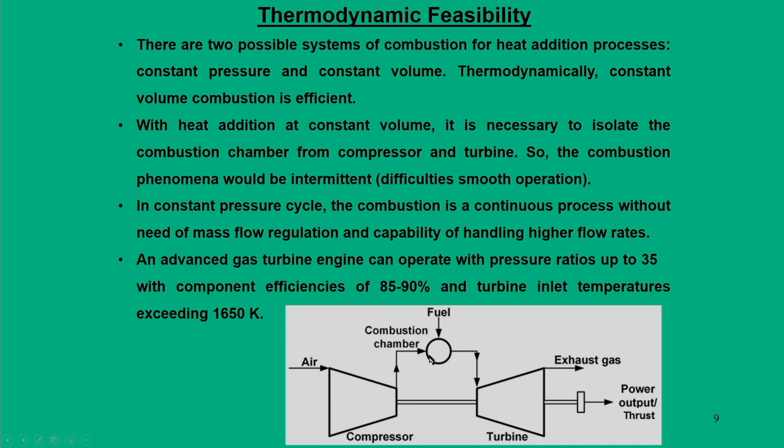Now, the question comes here. We have seen from IC engines that the heat addition from the fuel can be done through two different modes. One is, in the SI engine, a constant volume combustion; in the CI engine, we call this constant pressure combustion. Ideally both could be possible for gas turbine engines, but in reality only the constant pressure mode has a physical advantage, or many advantages.